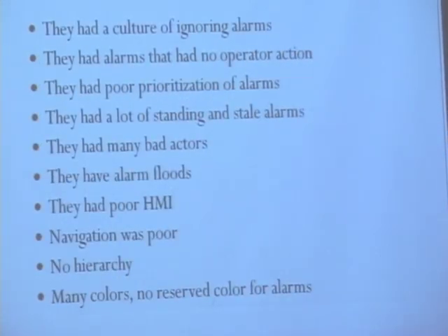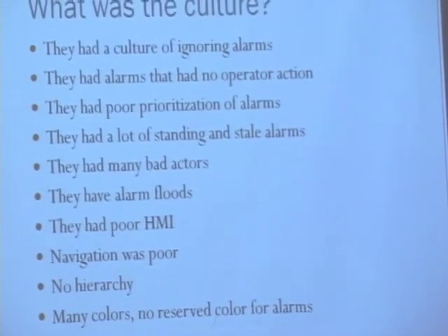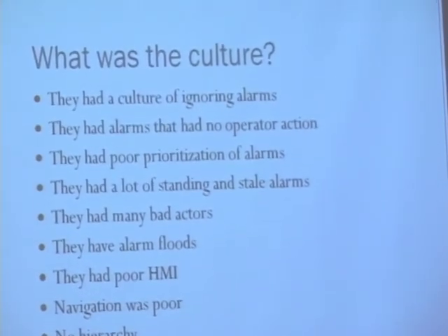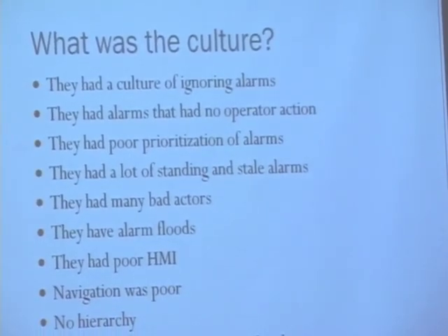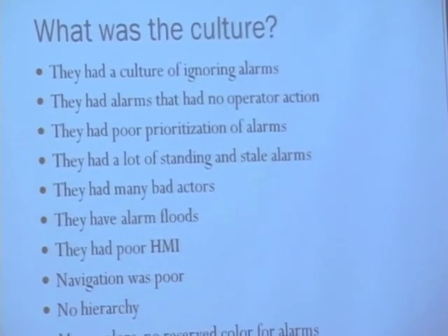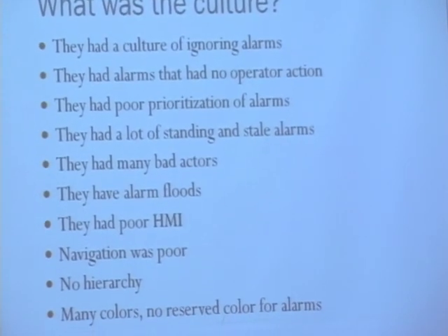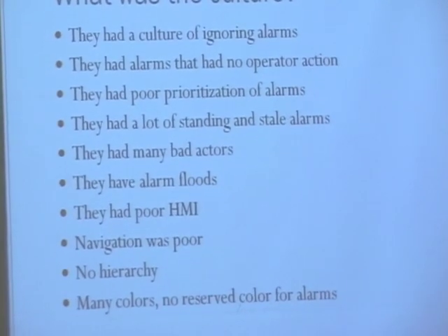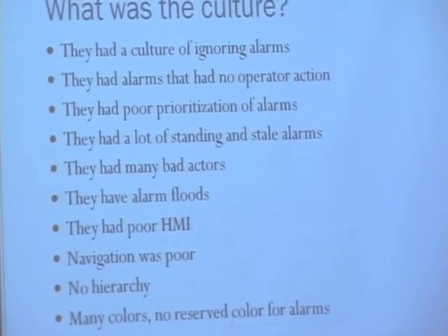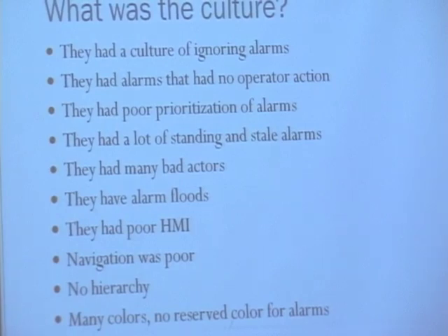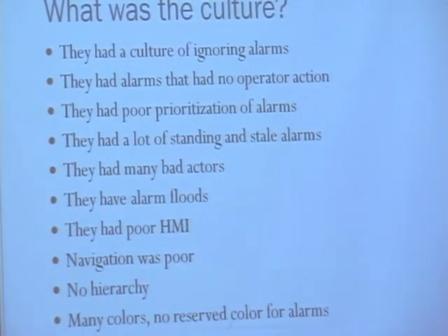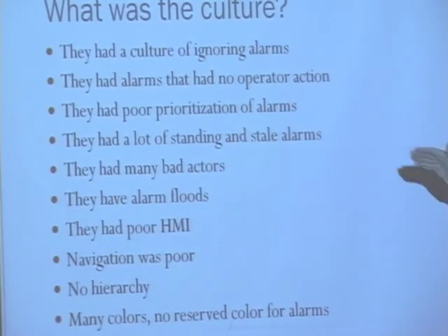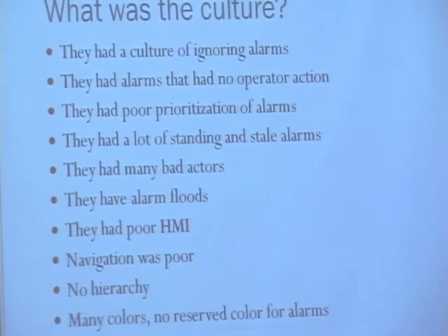But if we go back to Texaco Pembroke, and I don't want to pick on Texaco because Texaco is a good company, okay? They were no different to everybody else in the industry. But Texaco had a culture that ignored alarms. They had alarms that had no operator action. They had poor prioritization of alarms. They had a lot of standing or stale alarms, pages of them, and again I've seen similar things here this week.